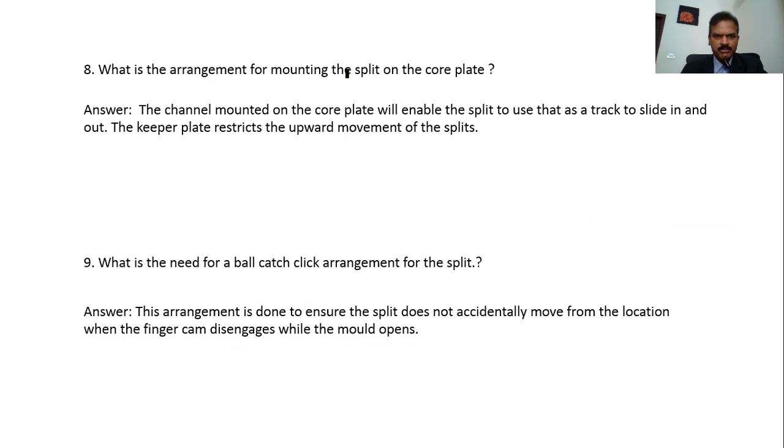So what is the arrangement of mounting the split on the core plate? It's the channel, and you use a keeper plate so that the split will not pop out. What is the need for a ball catch click arrangement for the split? You understood that when the finger cam disengages from the split, we expect the split to stay where it is, right?